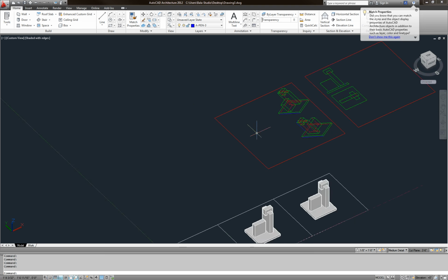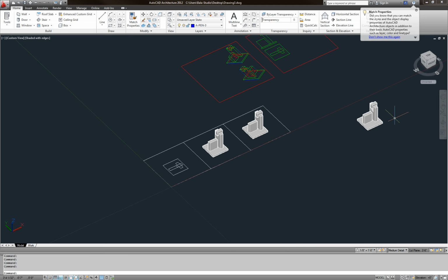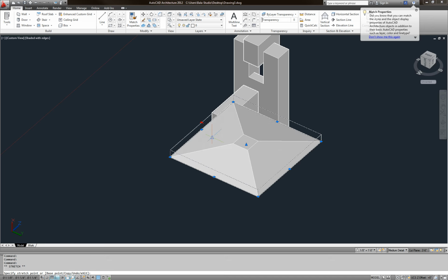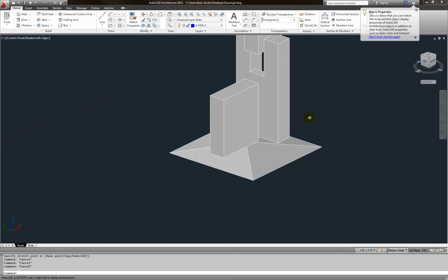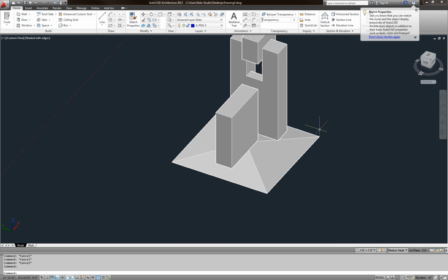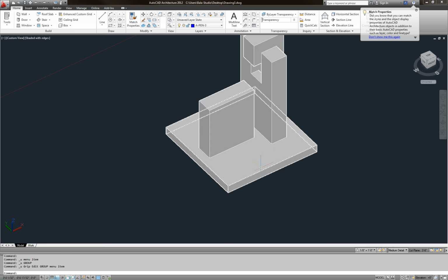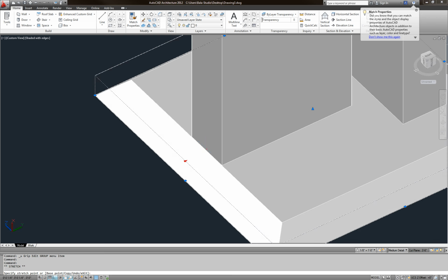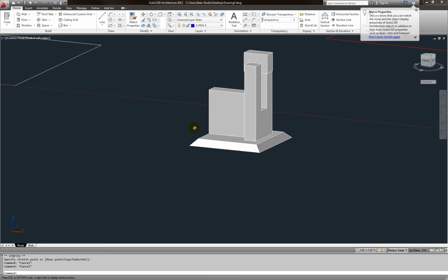And you could do the same thing with this. Over here you could make this whole thing go smaller, chamfer like this. Okay, you could make this a chamfer, or you could click on this and you could say let's make it up to here, so it goes like that.